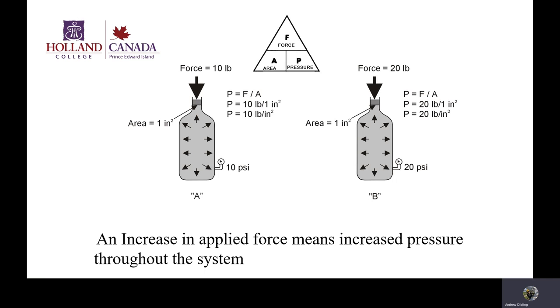Okay, so this is an example of Bernoulli's principle at work. I mean, force over area is pressure. And here we're using old, well, I guess American or British units, basically the only people in the world that use these. So if you can just suffer through them. You could imagine this being 10 kilograms of force at 9.81 meters per second squared, which is the acceleration of gravity, and you get 98 newtons. Regardless, 10 pounds applied over 1 square inch would equal 10 pounds per square inch.